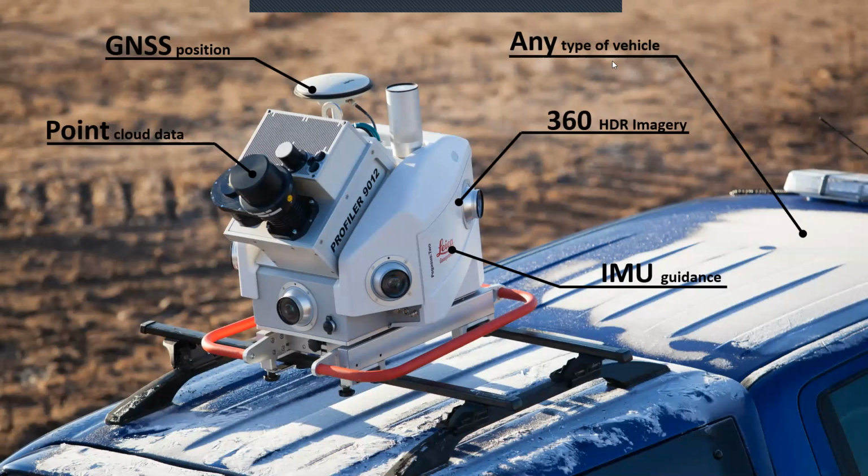And the scanner which you are now seeing on your screen is a Pegasus 2 Ultimate. This scanning system can capture at up to 100 kilometers per hour, so it depends how you drive the vehicle. Once the device is mounted on your car, it can be any car. It's independent of everything, has a satellite GPS system mounted on the device, as well as a point cloud capturing rotor head, which can go up to 1 million points per second, and multi-sensor cameras.